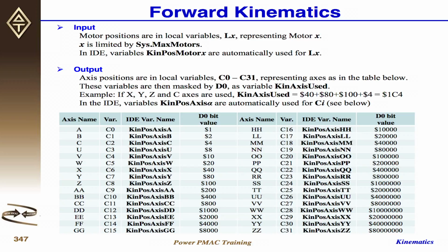So we have this double pass structure in here in forward kinematics. If you don't want to use these 2 online commands to query the current velocity or the current following error for a specific axis, then you don't need this. But usually, you don't really know in the future if you want to use it or not. So we usually put it in here in the template for the forward kinematics.